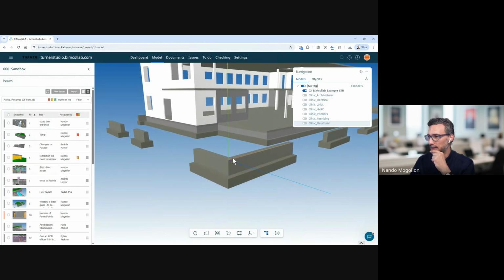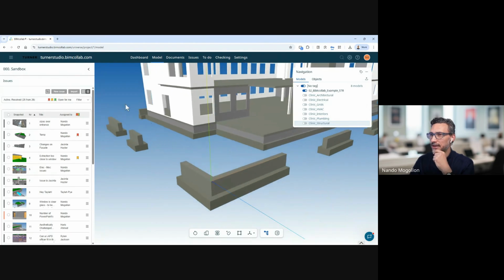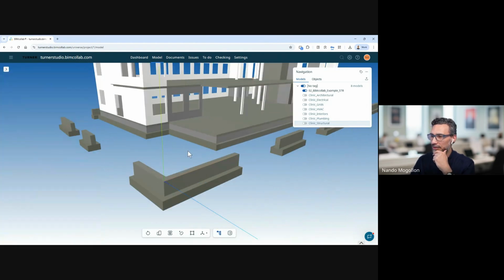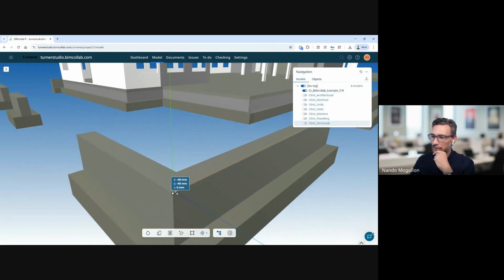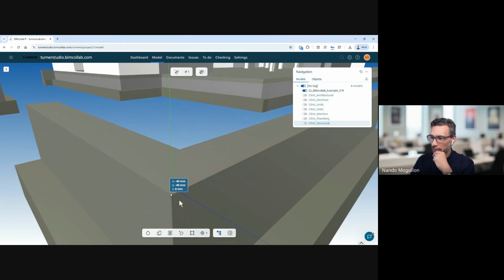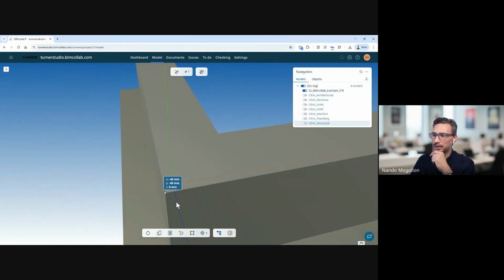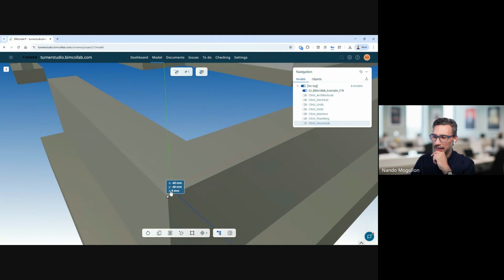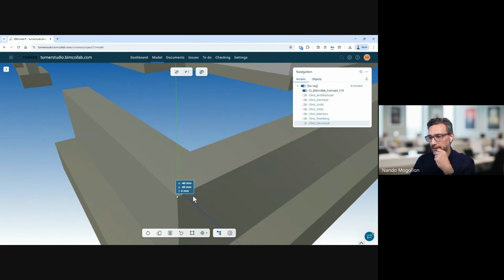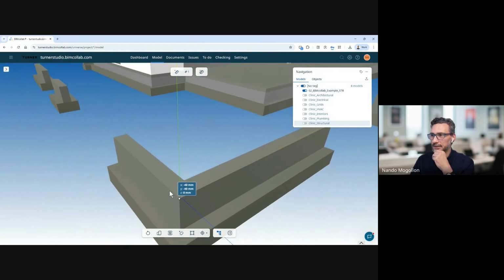I can see the origin in there, but in here you have an advantage. The advantage of the online viewer is that under the measurement tools you have a coordinate measure. If you click on the corner here, it will tell you the coordinates of that point. Looking at that, X and Y is minus 40 millimeters, and it's flat at the surface, flat at 0.